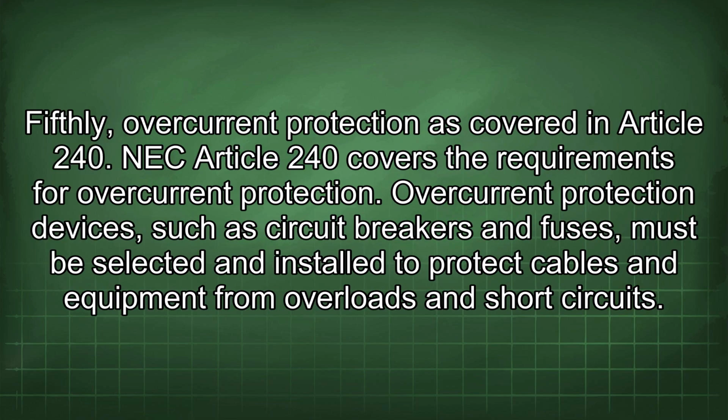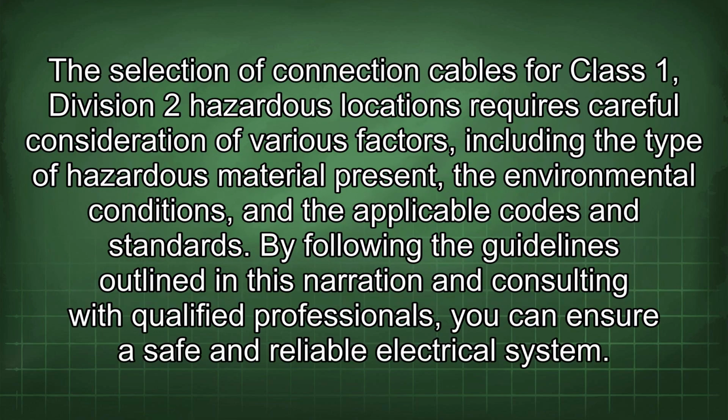Fifthly, overcurrent protection is covered in Article 240. NEC Article 240 covers the requirements for overcurrent protection. Overcurrent protection devices, such as circuit breakers and fuses, must be selected and installed to protect cables and equipment from overloads and short circuits.